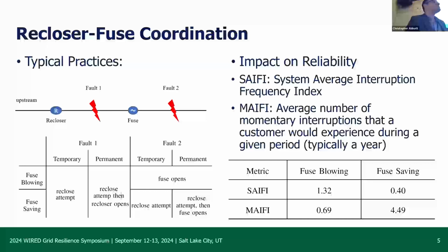Reclosers are usually operated by a time overcurrent element, and they have this reclosing option. Reclosing is useful because 70% of the faults in power grids are temporary. For example, assume a bird flies and sits on a power pole and spreads its wings. We have a fault. Fortunately, the bird dies and falls, and the fault is cleared. That happens a lot. Unfortunately for the bird.